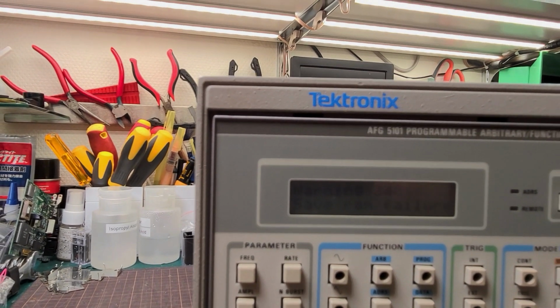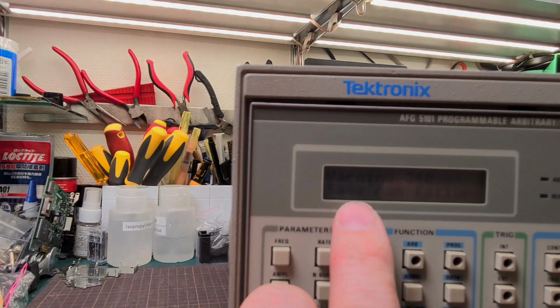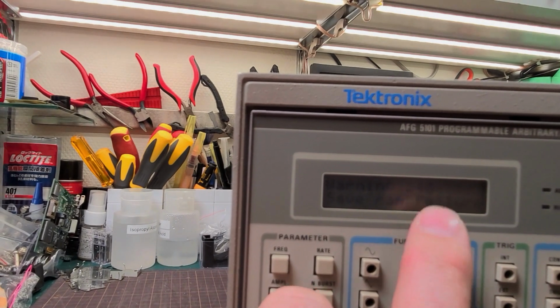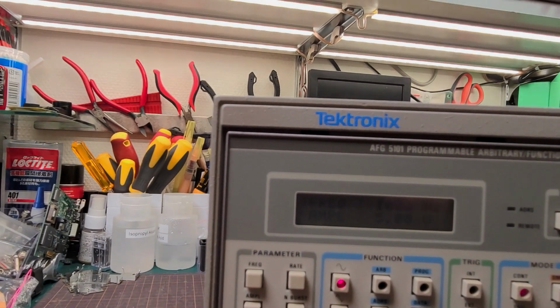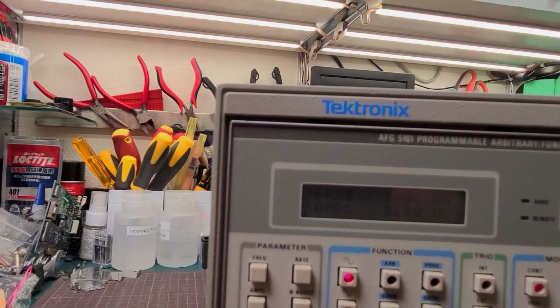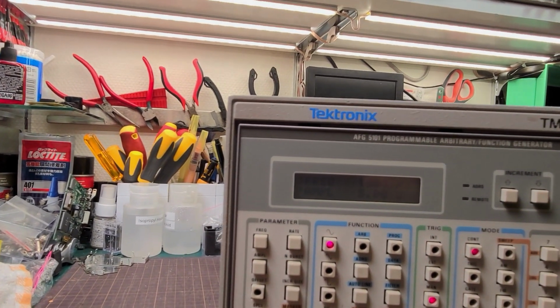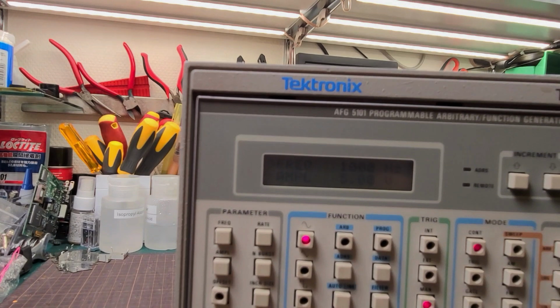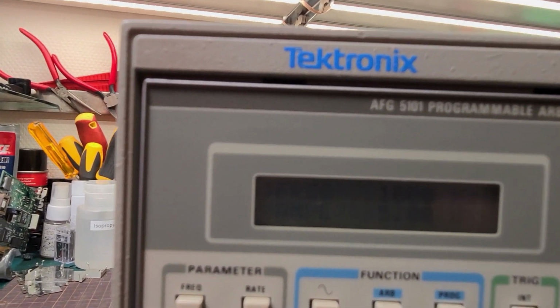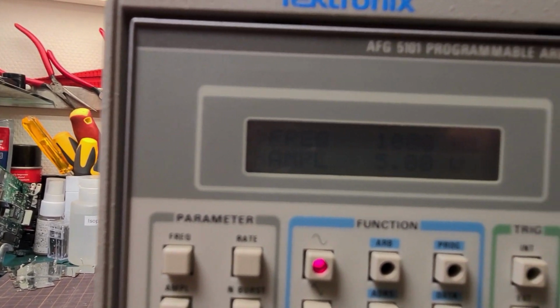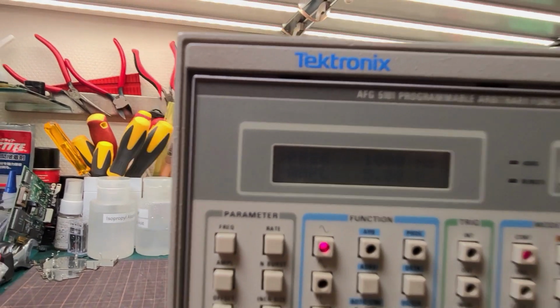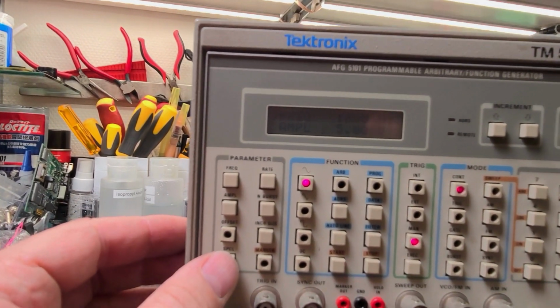V81.1 version 1.2, save RAM failure, error 340. Okay, now I have to look at that. That may be the battery, maybe the RAM's just getting cleared because there's no battery backup, so we'll have to figure that out. But it is showing a screen. I don't know if you can see that. That is really, really bad. That's so faded. Let's see if we can turn the backlight on.